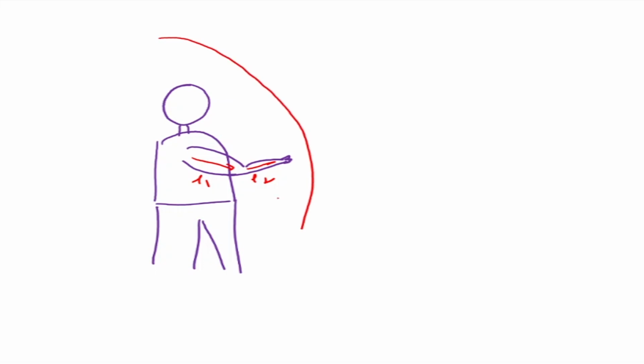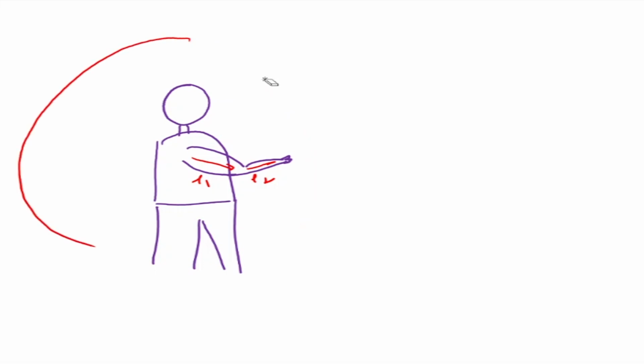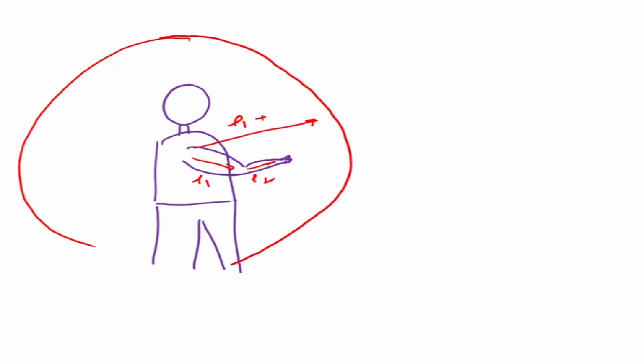The third is, I just mentioned that for a human being it's a very interesting example also. If you consider this to be our arm, and this is my hand, then our work volume is very large. It's a sphere, right? I had drawn this. This is L1, that's L2. So my work volume is going to become a sphere of that shape, spherical, with radius L1 plus L2.